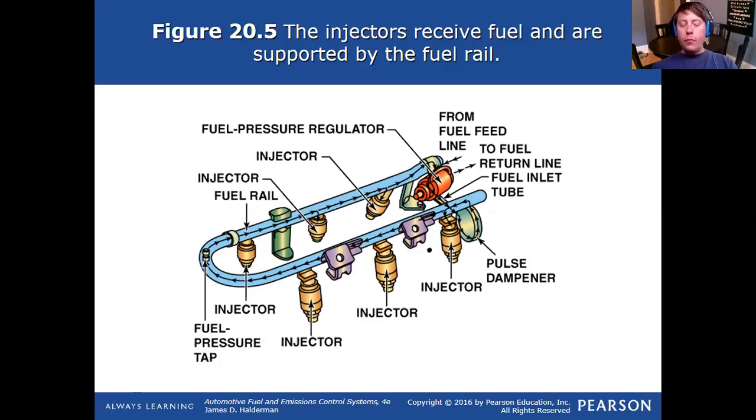So if you have that increase and decrease in fuel pressure and volume because you're opening and closing the injectors, and you have a fuel pump that's on, off, on, off, on, off, you don't have a consistent fuel delivery to that injector. When that injector goes to open, it might not get the exact same amount of fuel into it every single time. And so that decreases the efficiency of the entire system. The predictability kind of goes out the window.